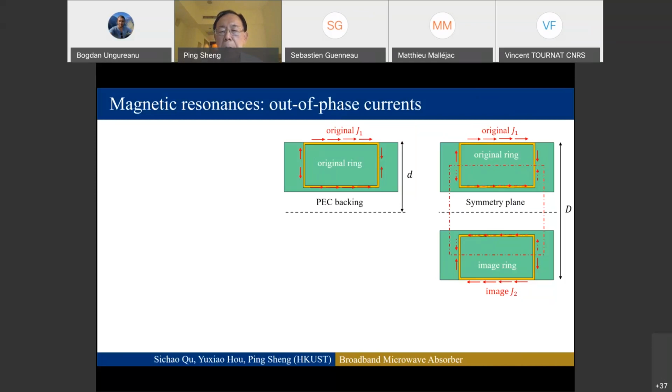Why is that? And the big distance D here is 28.4, namely twice the small d, because at high frequencies, we have to consider the retardation effect, of course. So what I've drawn for you, of course, is essentially the static or the low frequency limit behavior. But at high frequencies, the retardation means we have to take into account the phase. Essentially, the current flow on the top, J1, is going to send out a signal through the vector potential, and it is going to travel at the speed of light to the bottom, essentially to the image, to J2. And we have to take into account the effective index of refraction, and the signal had better be just in phase when it gets to J2 with the signal sent out from J2, so that they reinforce each other.